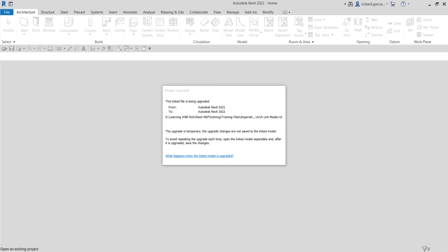In this series of lessons, we're going to begin the construction documentation for the building project. We are going to learn how to create a duplicate plan view and apply a view template. After that, we're going to learn how to create dependent views, place match lines, and view references. Then we're going to learn how to create a plumbing isometric riser from a 3D design view, and call out views for a typical HVAC view and a detail view. All right, so let's get started.